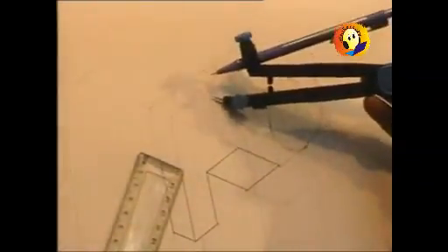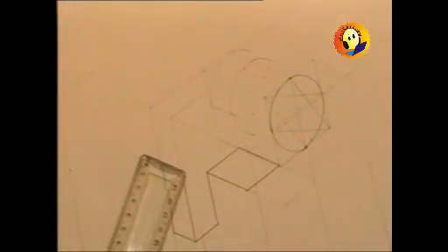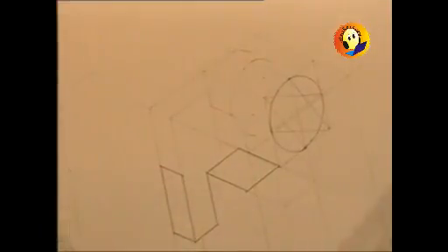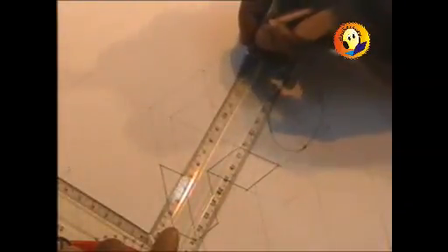This is of course the circle on the back plane, and that portion will not be seen. And now I am required to draw a tangent, and how to draw tangent, that is another question, because from this point it should be tangential. Of course it is going to be through the observation only. There is no other way that any measurement can be taken and the tangent can be drawn. And so we are required to draw tangent from this point to the 30 mm shifted center, which is our ellipse, to that ellipse we should be drawing the tangent.